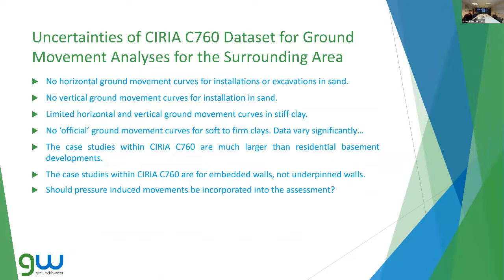Now we'll move on to something a bit further away from what you can do and more what you can use from. There are ground movement curves in the CIRIA C760 document where there's quite a lot of data, but mainly for stiff clays. So, for example, as you can see here, there are no ground movement curves for excavations in sand or installation of walls within sand.